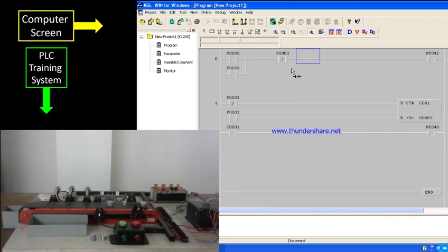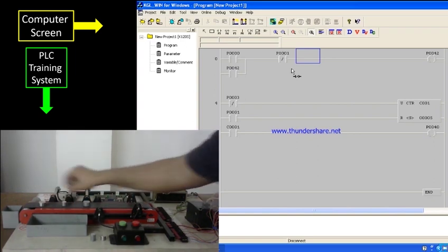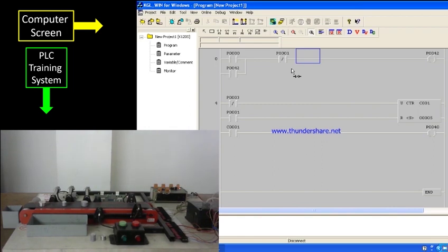Up to now we have seen that the conveyor moves in an anti-clockwise direction. We can also have a clockwise motion. For that we need to use an output of P43. For that case we need to place these items on the left hand side of the sensor, and keep in mind that to have P43 we also need P42, because P42 actually activates the motor and P43 just reverses the direction.